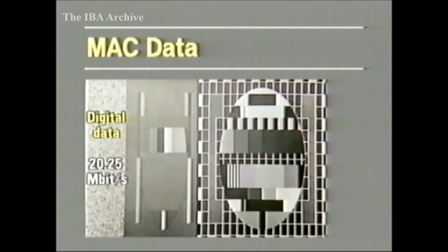Each burst of data is broadcast at a rate of 20.25 megabits per second. That's about 3 times the rate of teletext pulses. The data signal is present for only about 10 microseconds during each 64 microsecond line period ahead of the picture signal. This gives 206 bits of data on each line. An exception is line 625. This is made up entirely of digital data, 1296 bits instead of 206.